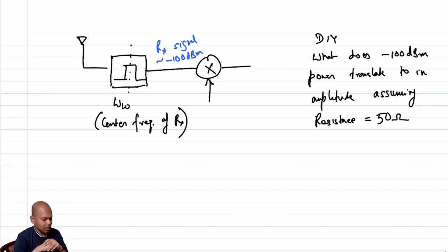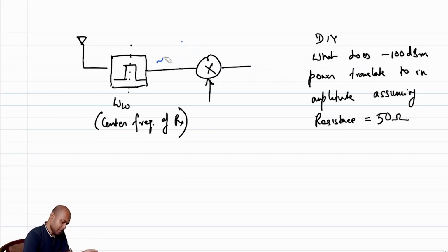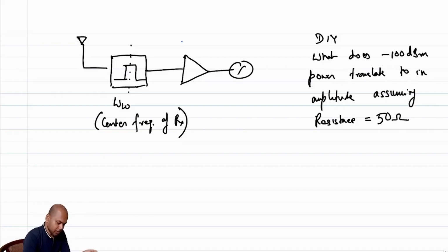So having only an amplifier is not a solution. You need something which not only amplifies your signal but also does not add too much noise. That is why, at a very system level, we can assume there is an amplifier which needs to be added before your signal goes in, and we typically call this a low noise amplifier.